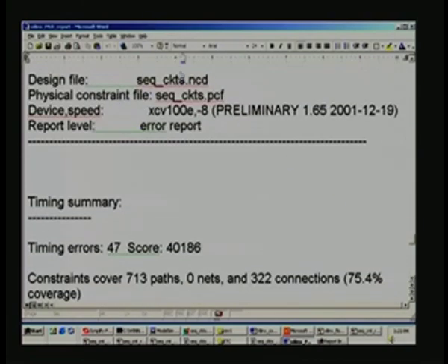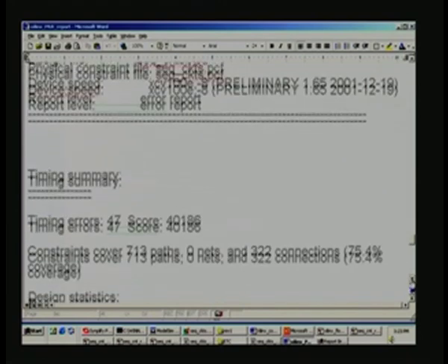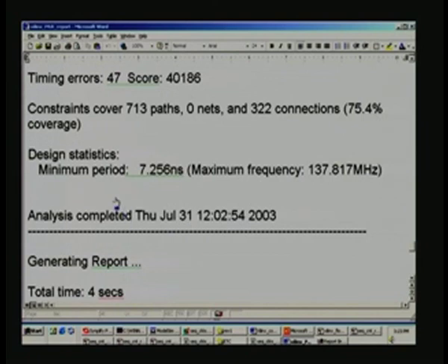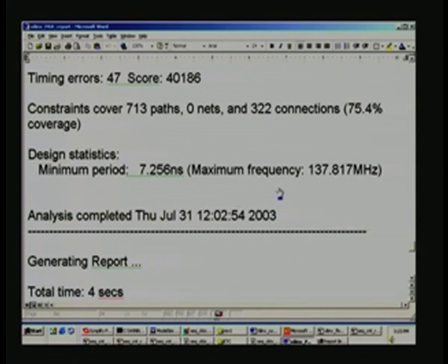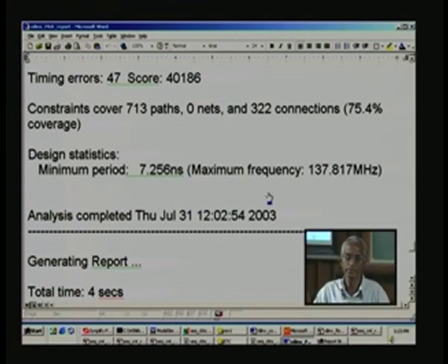These are all the intermediate files. Right now we need not be concerned about them. And here comes the frequency of operation. You see it's surprisingly higher here. As I mentioned, for smaller designs, my observation is synthesis will be very conservative. But real designs are all big, so it will be the reverse. Normally synthesis will report say 100 megahertz, but place and route can give only some 80 megahertz. That is the usual scenario, whereas here it appears to be exactly the reverse, and I think we started with 116 megahertz in synthesis.